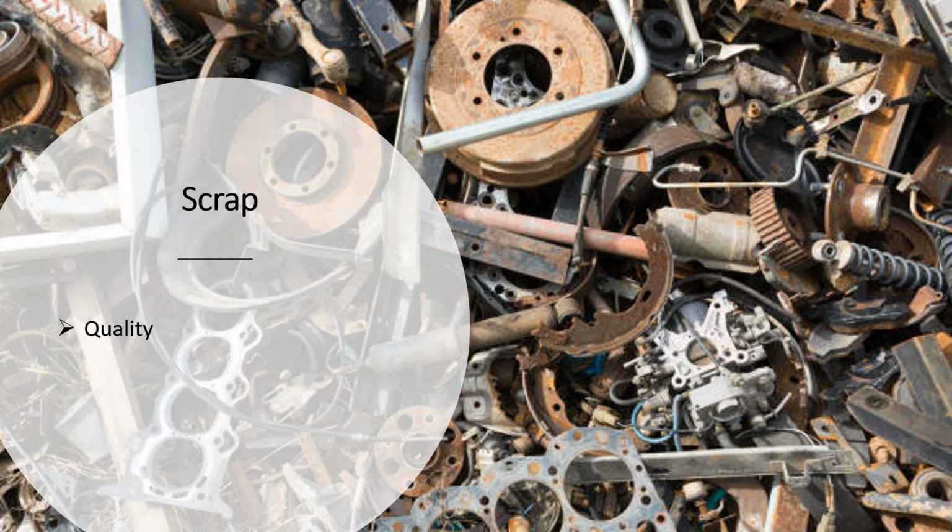So understanding quality as early in the process as possible, and at any time throughout the process as well. That's for the manufacturing side, but this also happens on the parts side, meaning the parts I'm purchasing from my vendor. If those parts meet my quality specifications, that's great, I'm going to put them into the hopper and they can get used. If I do my testing up front when receiving, and I find issues, I can immediately discard those parts so they don't even get into the manufacturing process.